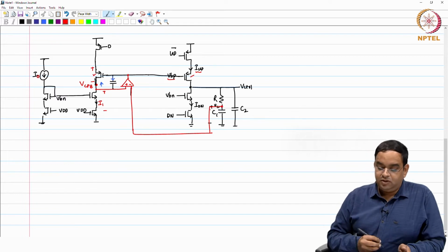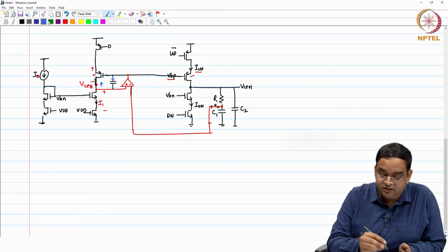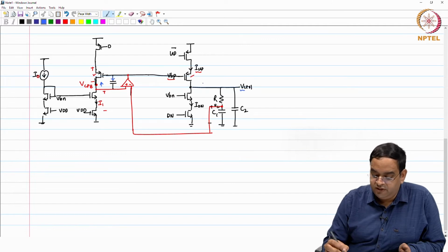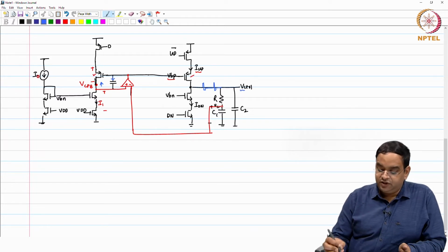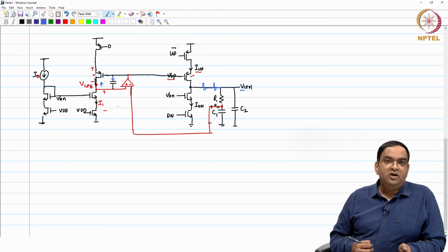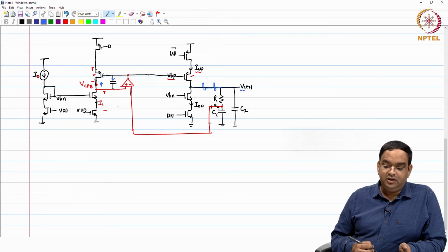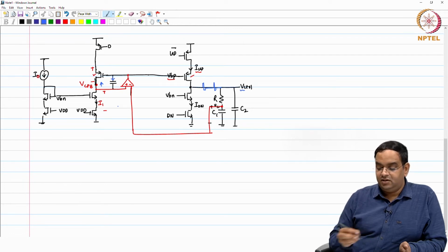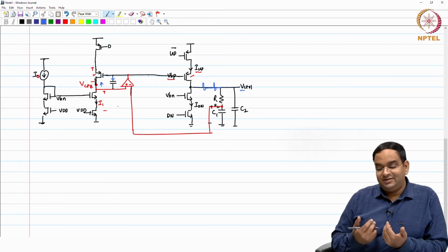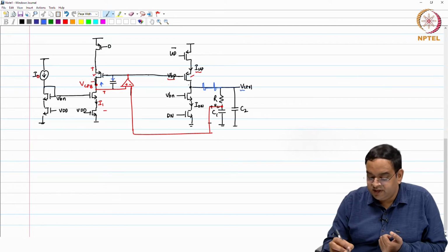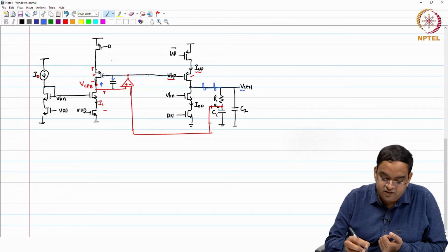So, the regular disturbances at your V control, every time you have a reference clock, you may have some kind of current. These regular disturbances are actually suppressed at the VC1 node. So, this particular loop will not be acting on the frequent disturbances, and this helps in minimizing the ripple on the V control, or the disturbances because of the PLL and because of this loop itself.